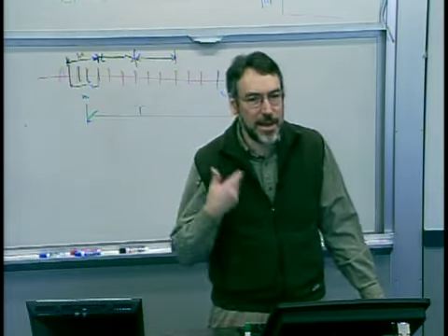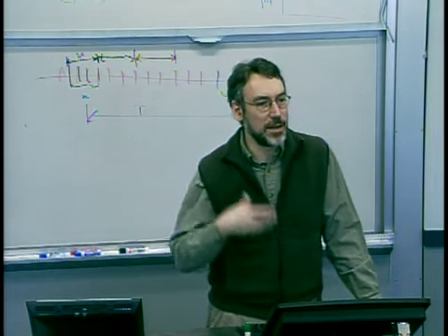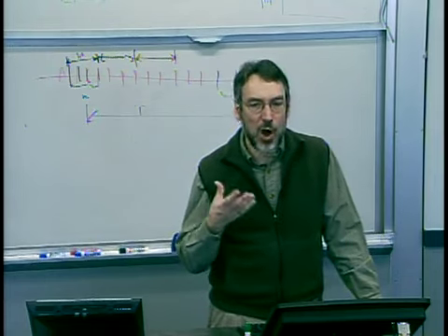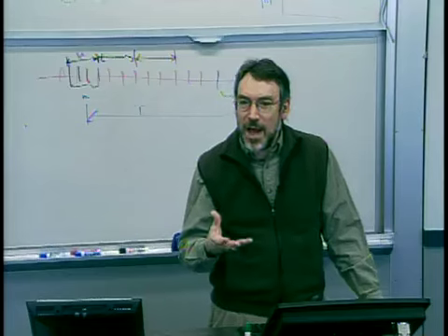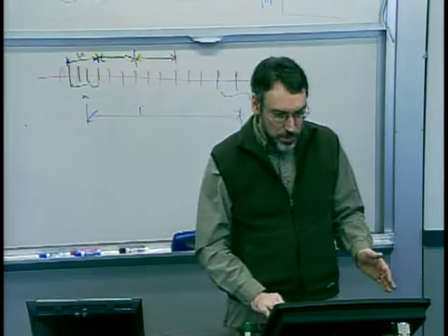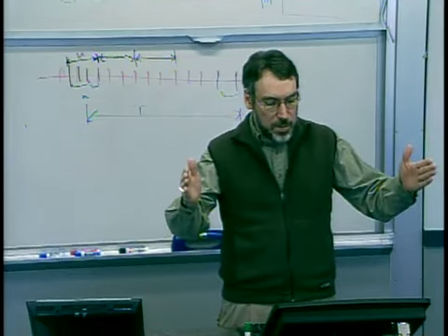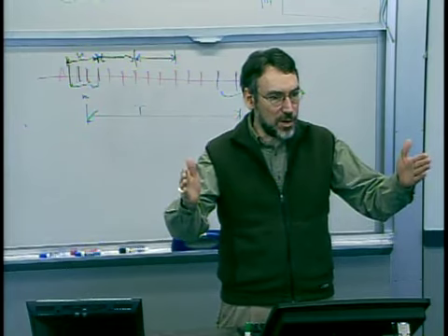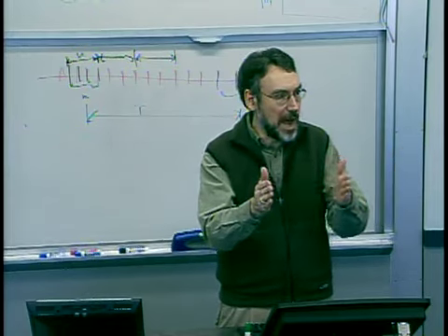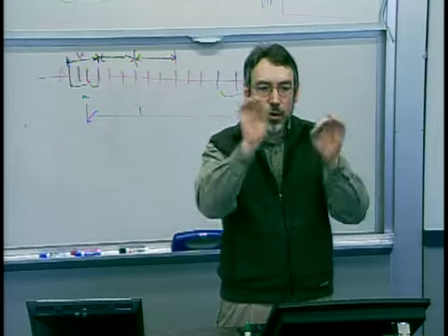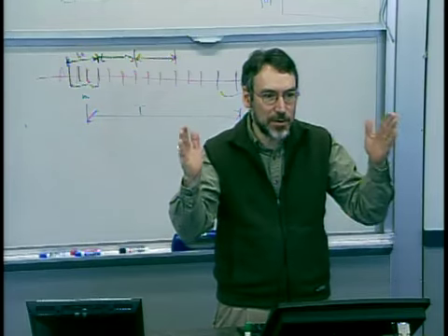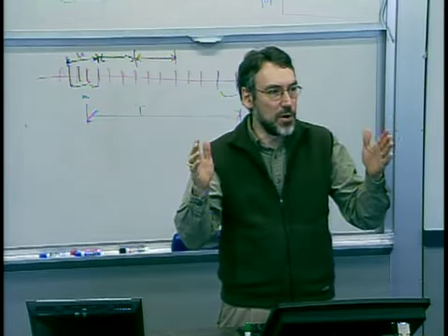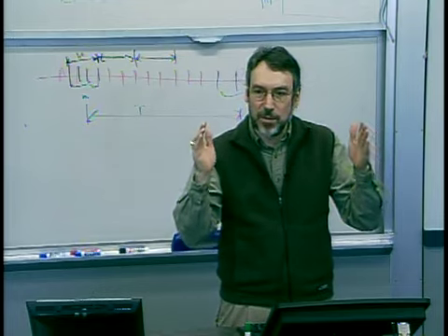And essentially a very nice canonical way of talking about how far apart your spec limits are compared to your distribution, how good your underlying process is compared to your spec limits, is this notion of process capability, or CP.